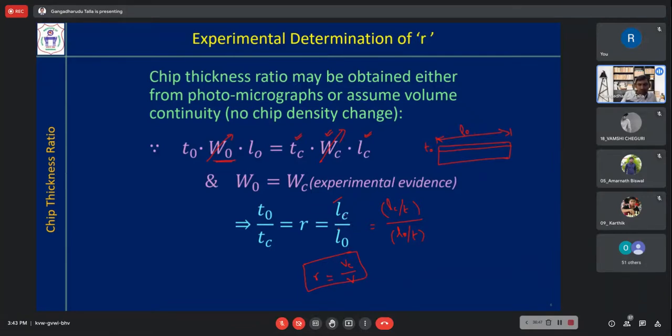Okay. Now you can find the length LC because once the chip is removed, you can find its length even though it is in this kind of form. You can measure the length of it using some microscope. You can project this on some surface and measure the length of a curve.